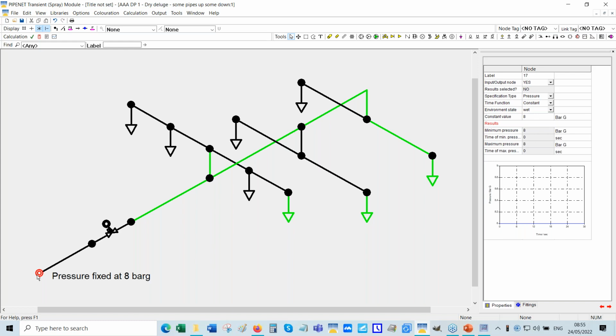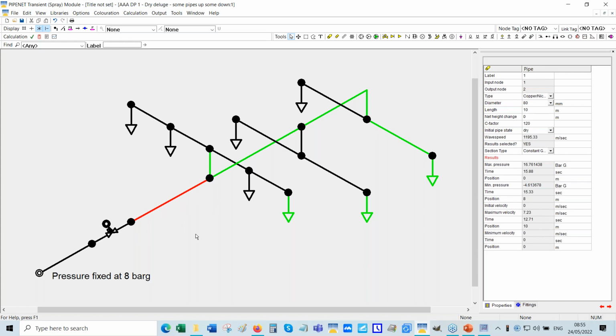So it is good engineering practice to avoid a big elevation change, especially the pipe that goes from the deluge valve into the actual fire watering main, the fire water deluge system proper.